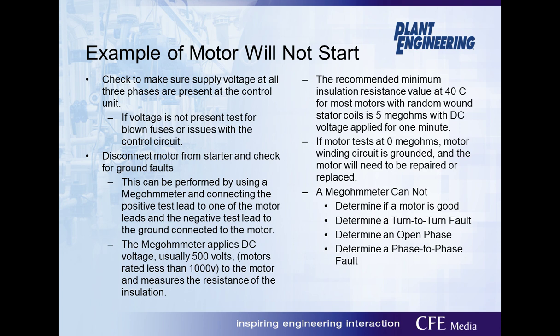Low readings may indicate reduced insulation conditions caused by contamination or deterioration from excessive heat over a period of time. If the motor tests at 0 megohms, then it's a given the motor winding circuit is grounded and the motor will need to be repaired or replaced.